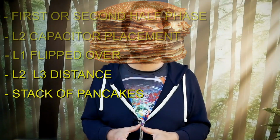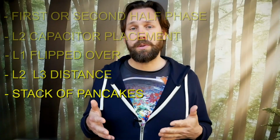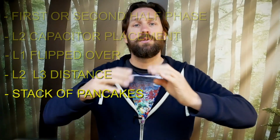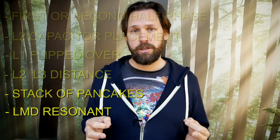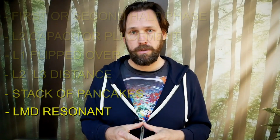The coil stack has parallel resonant L3 in the middle, close coupled to L1, while L3 is loose coupled to series resonant L2. L2 and L3 are LMD resonant, whereby they are 180 degrees out of phase. The circuit that I used is a solid-state Tesla oscillator.